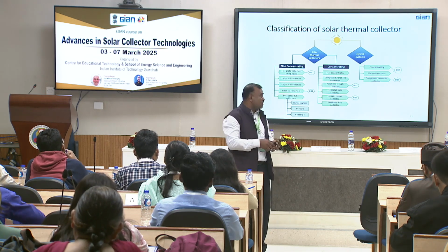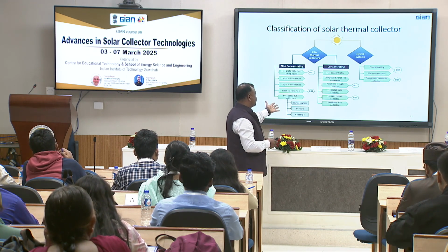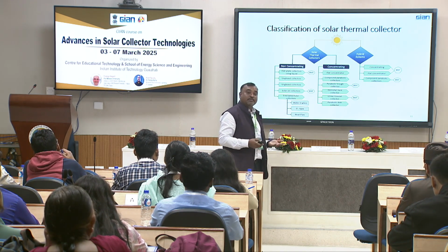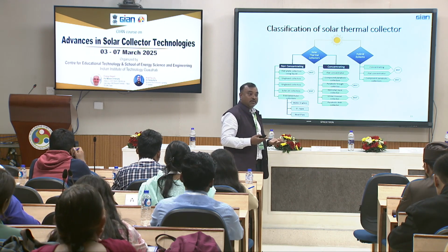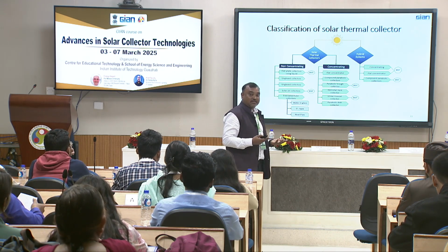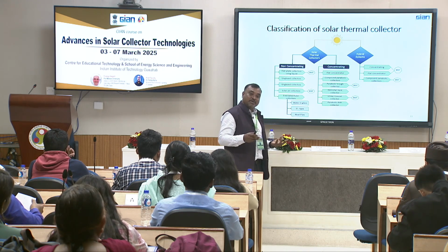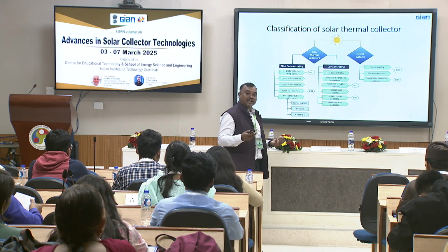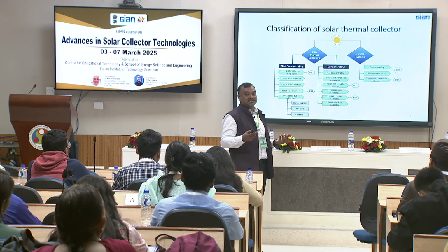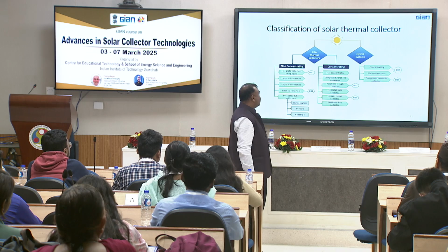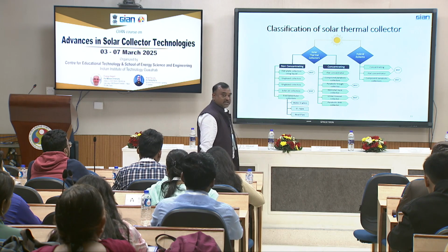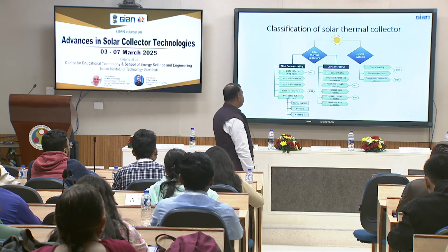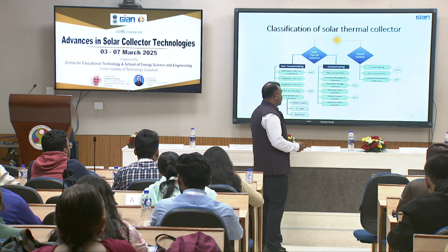Okay. But in case of parabolic trough or maybe linear Fresnel or maybe heliostat, you can go up to a temperature of 600 to 700 degrees Celsius. Okay. So it's a very high temperature. So it is something like our conventional Rankine cycle. So for information, the maximum temperature we can provide to the Rankine cycle is 540 degrees Celsius, right? So that kind of efficiency, that means that will lead to an efficiency of about 35 to 40%. That is also possible to achieve by using technology like heliostat field collectors.